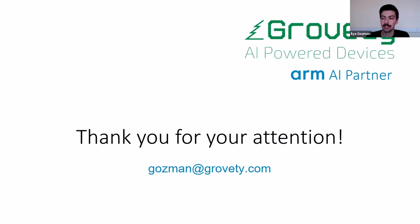From my point of view, and from our current projects, the main point for such hardware is not whether it's in-memory or some particular NPU. What I said is power consumption and the ability to control it precisely for our needs, to be able to save energy every moment. Currently, there are few such architectures open to the public. We found the ARM U55 very promising and it is our main platform for current research.